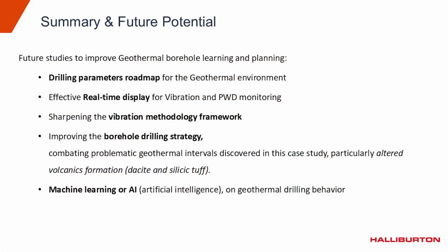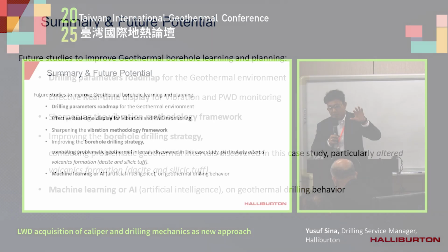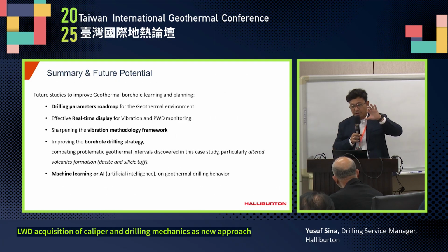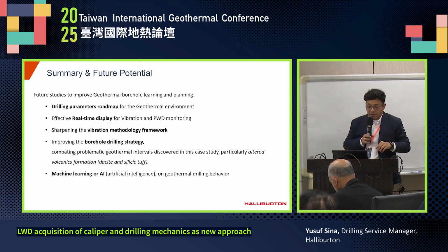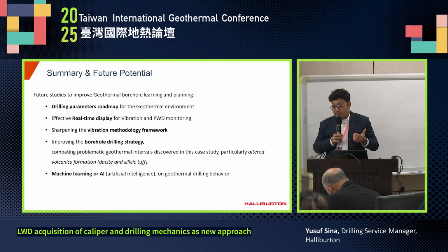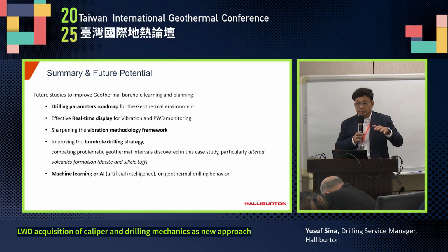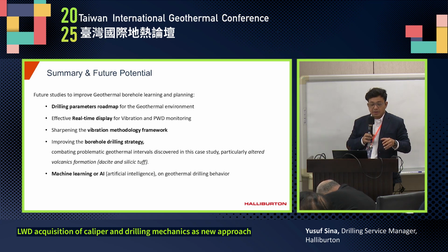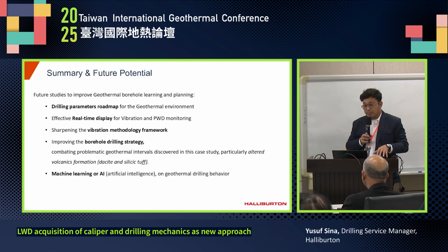Okay, so another summary and the future potential enhancements. The first one is the drilling parameters roadmap, because here we can see and benchmark the drilling parameters in terms of the vibration and downhole caliper data. The second one is the effective real-time display for the vibration and PWD readings. The third one, the vibration methodology framework can also be enhanced.